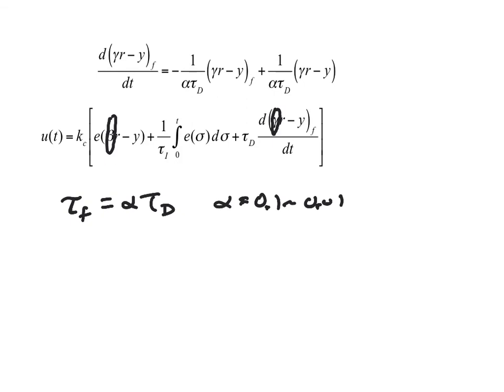The purpose of the beta factor is to minimize what we call kind of the bump that you get when you make a set point change, the proportional kick. And the gamma term is very often set equal to 0, so that we're only taking a derivative of the measured output. So beta is often reduced to reduce the proportional kick.